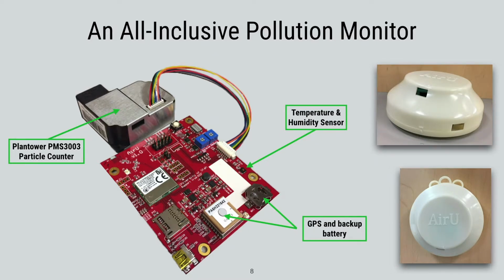And then through our first deployment, we found that since the sensors are located on the exterior of the homes, a lot of them actually have really bad data or internet connections. And so to mitigate the loss of potential data going back to the server, we've included an SD card. In the event that the monitor does go offline, the SD card will collect data, and when the monitor eventually does go back online, all that data will go from the SD card back onto the server. So you won't lose any of the information.